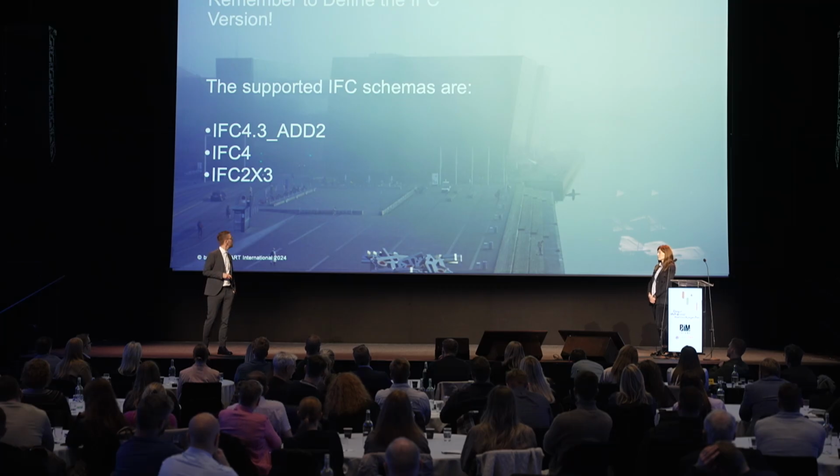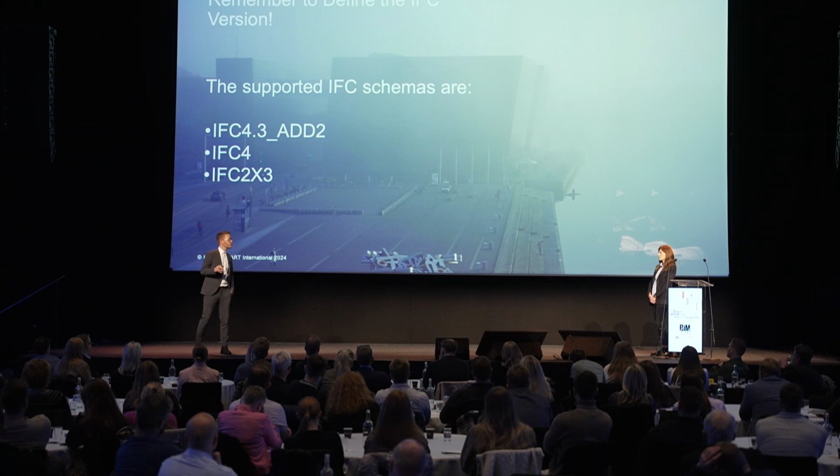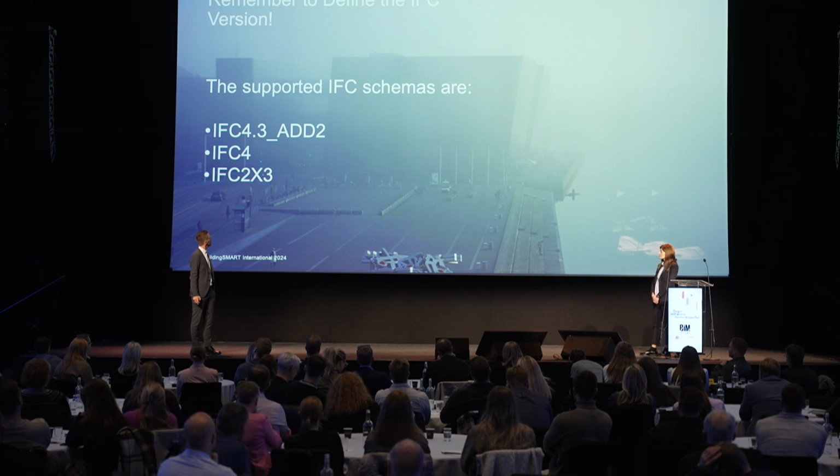We use IFC 4.3 because it supports infrastructure projects. It could be more difficult to use IFC 2x3 in an infrastructure project because every infrastructure object will end up in building element proxy. So you have to do a workaround there.